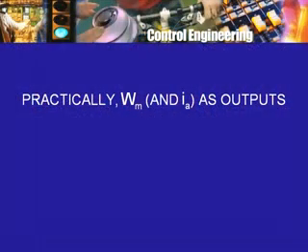The other two signals which appear as input signals in this signal flow graph are, from a practical point of view, at least one of them, definitely of the nature of output, omega m. We want the motor not only to provide torque, but to provide torque at a particular speed. Remember, the function was to have the motor run at some desired speed, constant speed. So omega m is a natural output variable.